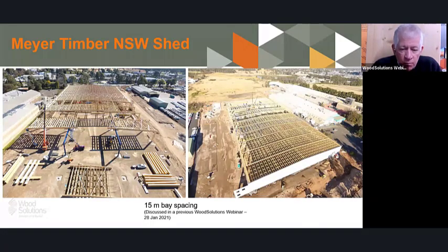And Kevin Nutella asks, what is the fire rating, the FRLs, of the timber columns and rafters? Well, this is a 1-storey building. There is no fire resistance for this one, but as you can probably guess, there is inherent fire resistance in the timber, but that wasn't part of the design because it was a single-storey building, Type C, away from the boundaries, so there wasn't any fire resistance required at all. And also roofs and structures in the NCC don't require any fire resistance. So thank you for those questions, and we'll move on to the next